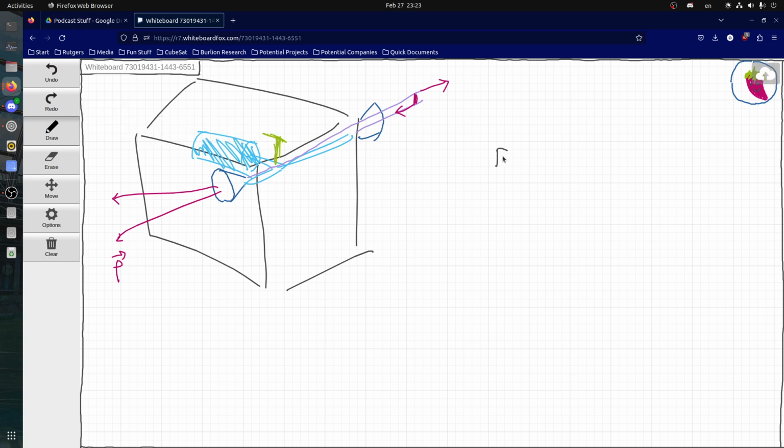In this case, we're using Newton's second law in this form, where the force is equal to the change in momentum, and the change in momentum is the time derivative of mass times velocity, but what we really care about is this m dot plus m v dot. And for a cold gas thruster, usually the v dot term is zero.